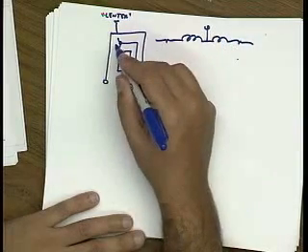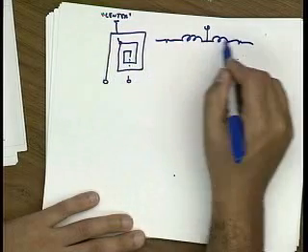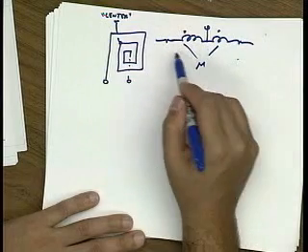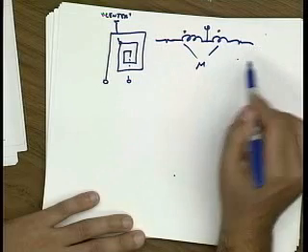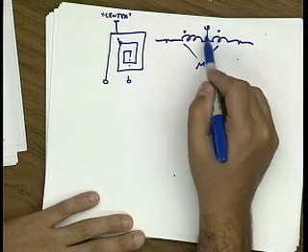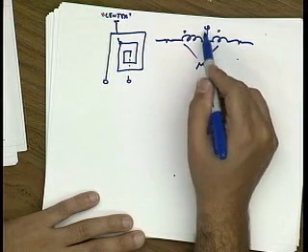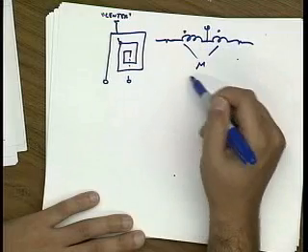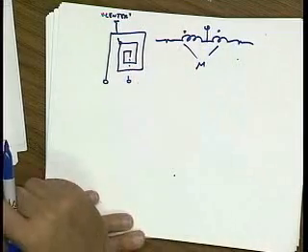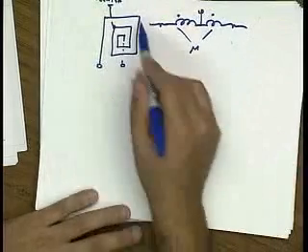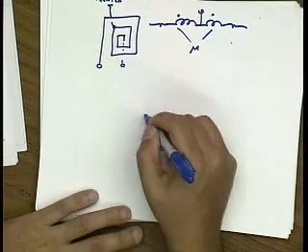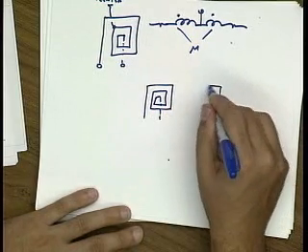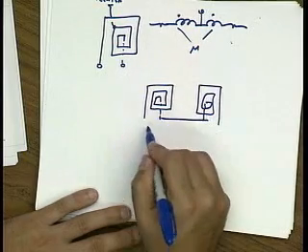So half the inductance, if you look at this as 2 inductors in series which are mutually coupled, then looking in from this path, I should see the same inductance as I do from this path, right? That way this point will be a virtual ground. If I actually choose the wrong point, then I won't have a virtual ground and I'll actually end up dissipating power into that node. And we'll see that's a big disadvantage. Okay? So this layout is actually not so good. One way to make this layout more symmetric is actually just take 2 inductors, let's say like this, and connect them like this.